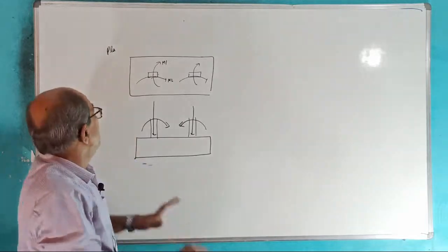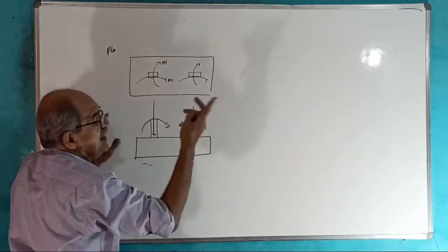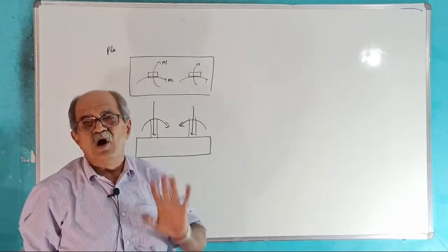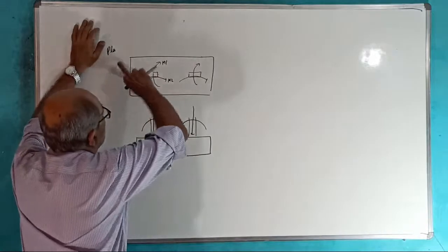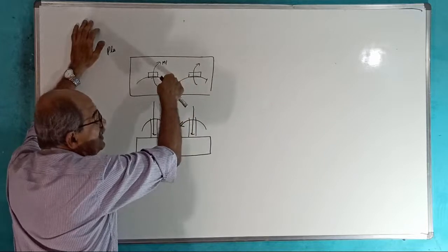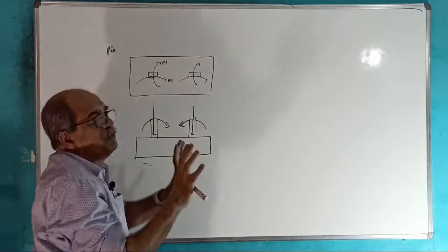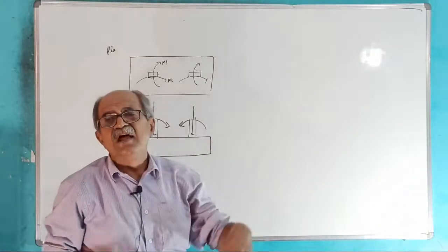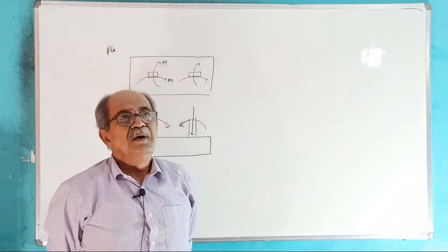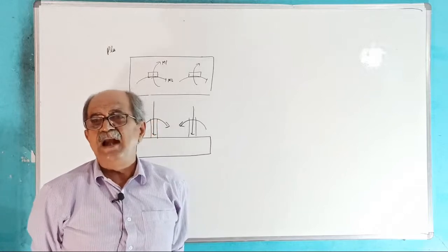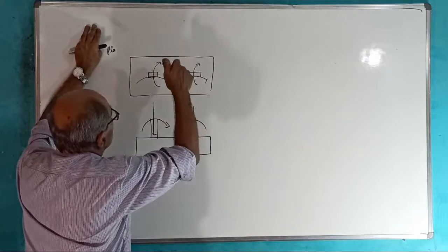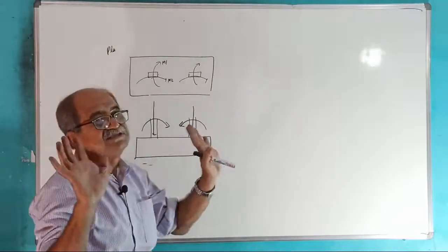In the same way, the moments you are going to get will vary. So, it is not possible to satisfy the condition of the resultant column load passing through exactly the CG of the footing. If it is satisfied for one combination, for another combination it is spoiled. So that theory of fixing the projection so that the resultant column load will pass through the CG of the footing is fully bogus.